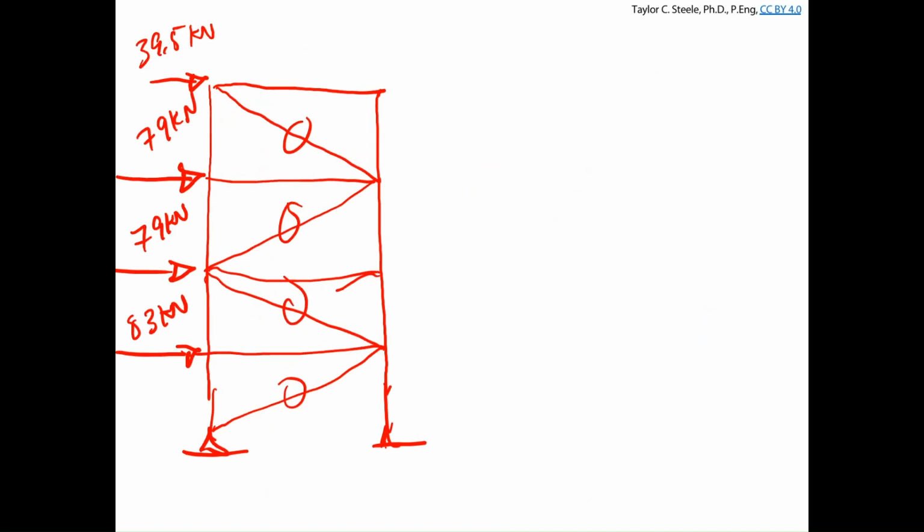Okay, so we've got a pressure pushing on the floor. We figured out how much it's pushing on the floor as a force per unit meter of the floor. Reaction is simple for the statics problem. It's just half the load, divided by 2, because it's symmetrically loaded in this case. If it was non-uniform, you'd have to do something a little bit different. But the problem here is not just to calculate that load, but it's also to draw it on a free body diagram of that braced frame.